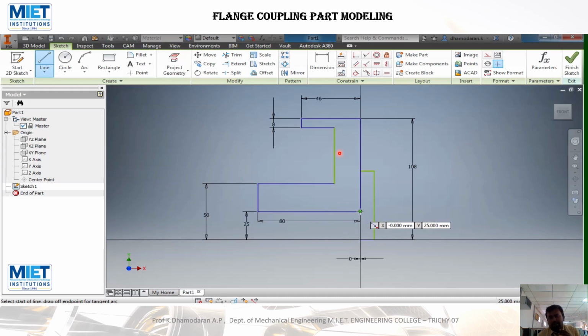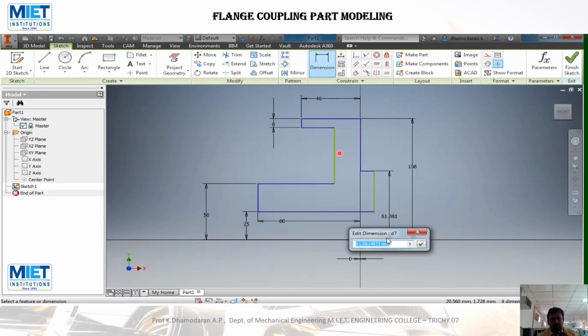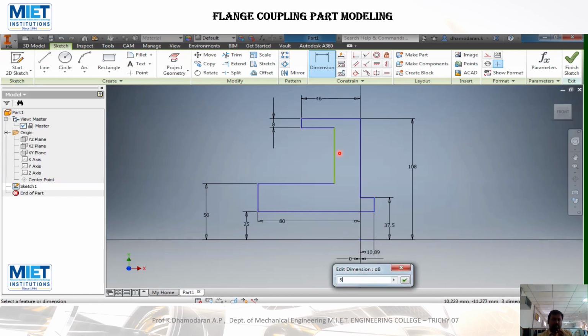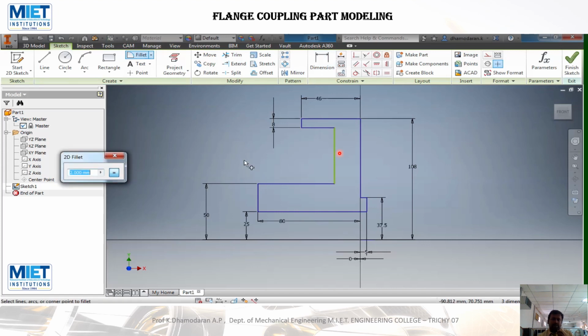This is the procedure. We start a sketch and proceed with a closed sketch. We are going to create a 3D model from the sketch. Only a fully constrained sketch makes it possible to perform the 3D model operations. As examples, 3D commands such as extrude and revolve are used to create 3D components from 2D sketches.